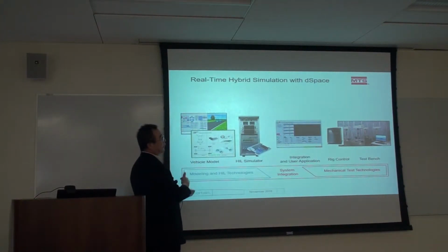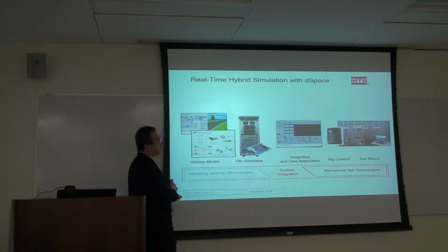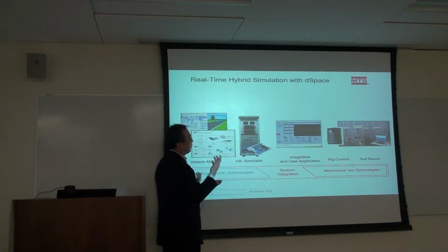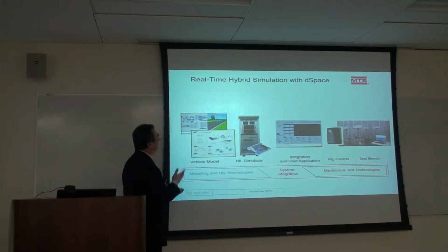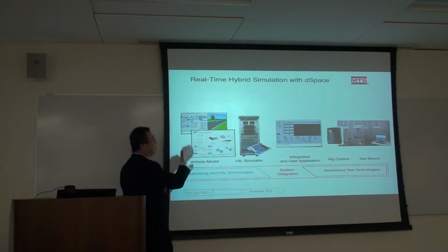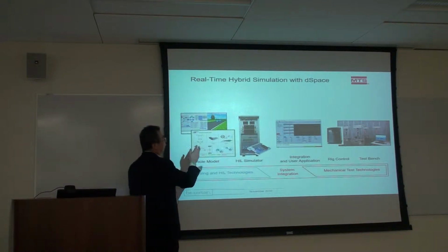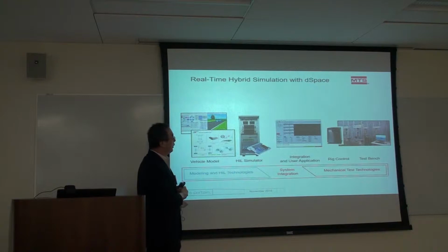To test this kind of complicated active damper system with electronic control, people started to use the hybrid simulation method. First you need a vehicle model and the proving ground, including all the substructures except the damper. This is an open seat for automotive.